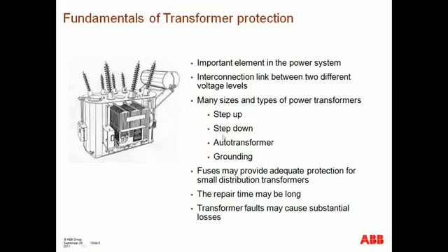The third type that's also commonly found would be an autotransformer, which, from a transmission network perspective, is a device usually utilized to interconnect two transmission networks that are operated at two different voltage levels. So, for example, if a utility operates a 400 kV loop and also operates a 230 kV loop, and you wish to connect those two networks, typically you would utilize an autotransformer, or perhaps a Y-to-Y transformer, which will allow you to connect those two voltage levels.